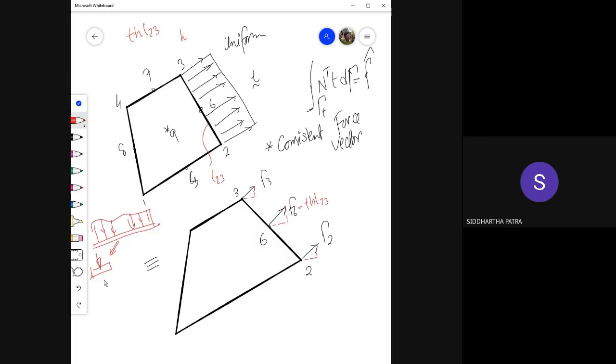But here there are two things to say. Number one, when we did this analysis in engineering mechanics, there we have considered only rigid bodies, we didn't think about deformation. And when we talk about the resultant, it's a single force. We can reduce this system to a single force because it's a planar force system. We know that a planar force system or a parallel force system, we can eventually converge into a single force system. The equivalent can be a single force system, but that's the understanding from the first year, first semester.